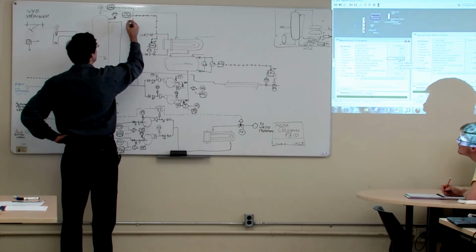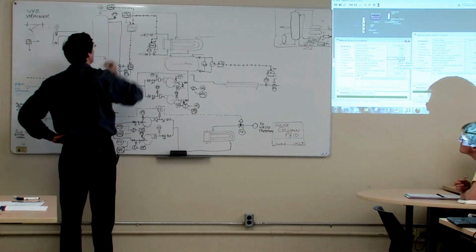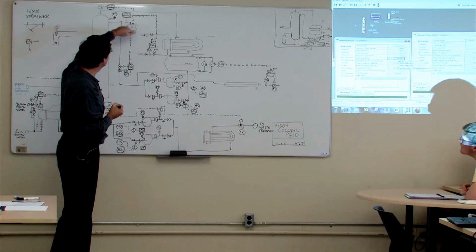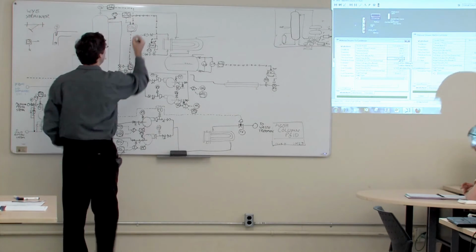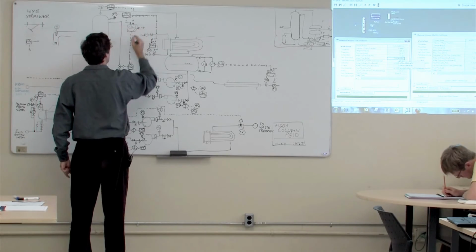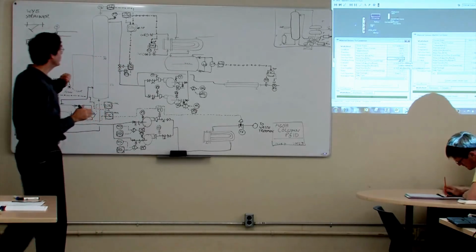So if the pressure isn't exactly where we want it to be, I can compensate for that in the software in the calculation of what the composition is. So I'm bringing temperature and pressure into my composition control. I'm calculating what the composition is, comparing it to a set point that the operators are determining, and sending the output of that controller into the flow controller on the reflux.